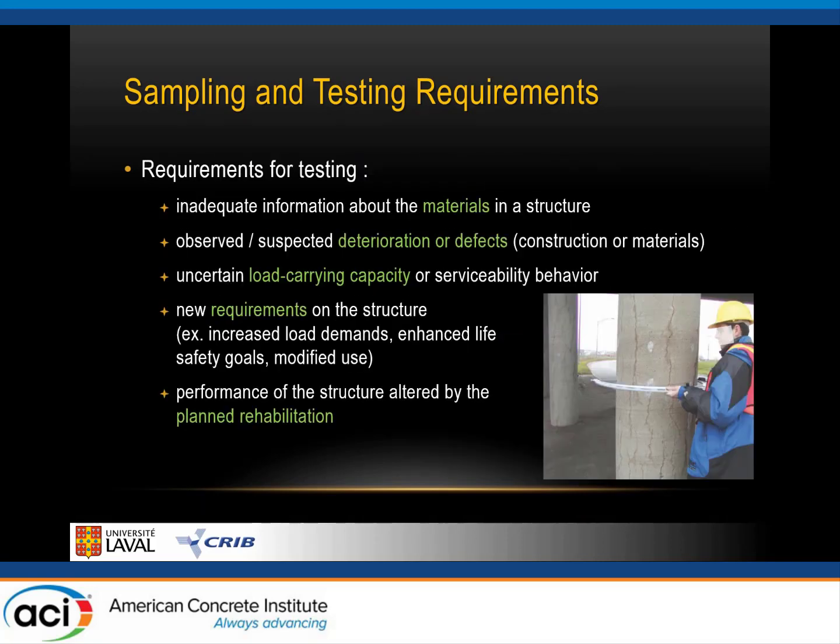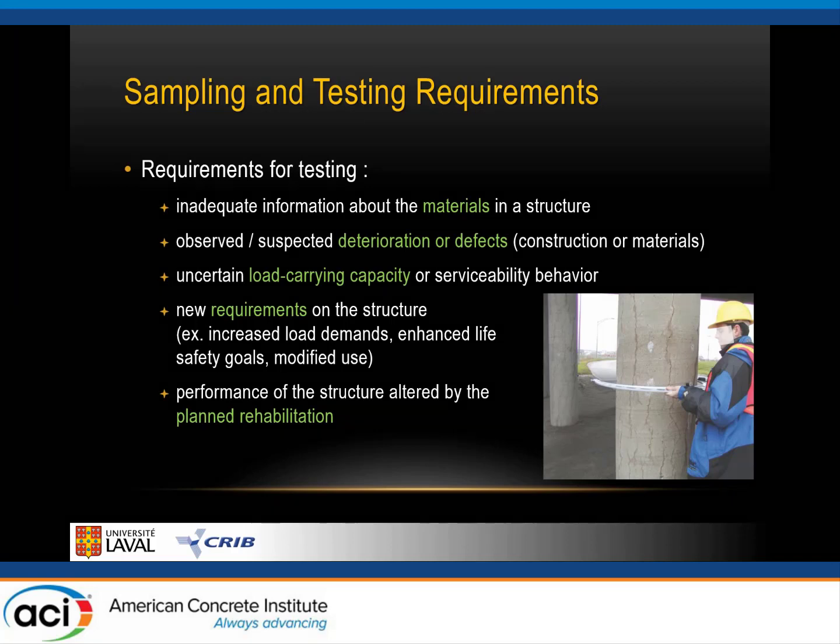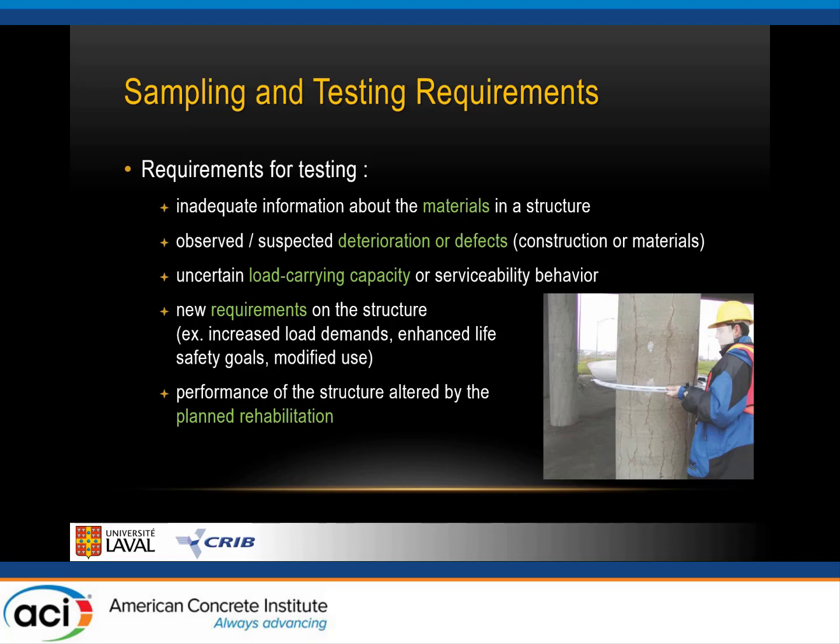The requirements for testing depend on the different needs. It might be to better document the condition of the materials, what the materials are, what the distresses, deterioration, or defects are that developed in elements or in the structure as a whole. It might be to support a load carrying capacity evaluation that is needed.